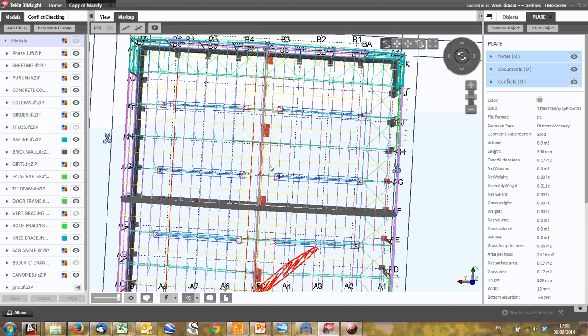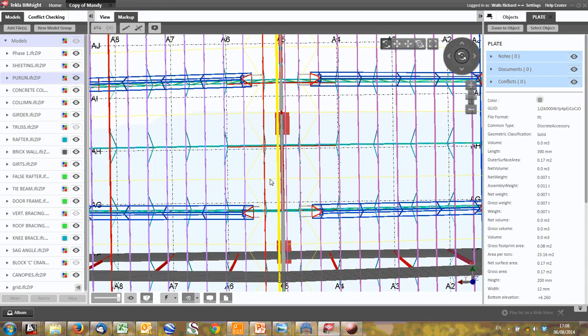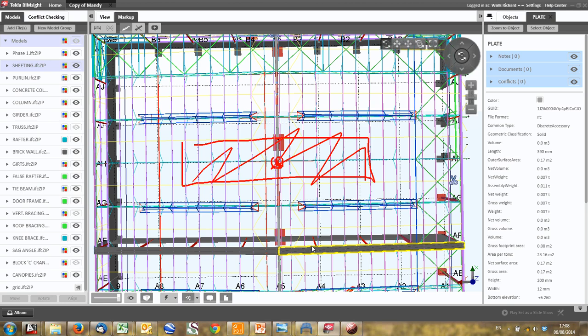So if we wanted to work out what is the load from this truss, what is the reaction down on this girder, once again, sort of half, and all of that would be acting on that one truss and providing a reaction force there in the middle. That way you can check your reactions, you can check your calculations, make sure there's nothing funny going on. Obviously, if this is more stiff in the middle, this would actually probably attract between 55 and 60% of the load. But it also depends on the stiffness of the outer columns and various other things. So it's half, but obviously the stiffer areas do attract more, so we might add on a little bit there.